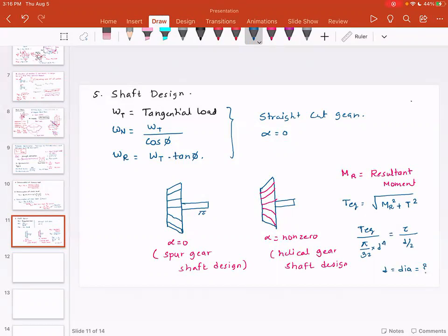So in terms of shaft design, the process is similar. The only thing what you want to take into account is what type of support the bearing has. If the bearings are cantilevered, means the gear is supported only on one side, or you have bearings on the both sides of the helical gear. In other words, the helical gear is supported in a simply supported shaft.